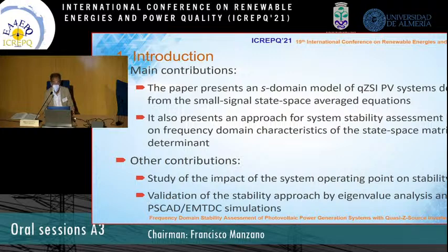Once we have the model of the system, the paper also presents an approach for system stability assessment, based on the frequency domain characteristics of the state space matrix determinant. Minor contributions of the paper are the study of the impact of the system operating point on stability and the validation of the stability approach by the eigenvalue analysis and PSCAD simulations.